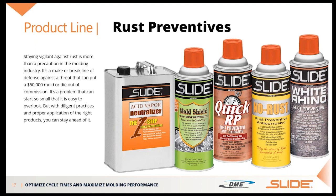The no rust, the yellow can, that's a heavy duty rust preventive. It goes on with a brownish-yellow tint to it. It's a 5-year rust preventive, and you will have to clean it when you put the mold back on the press.